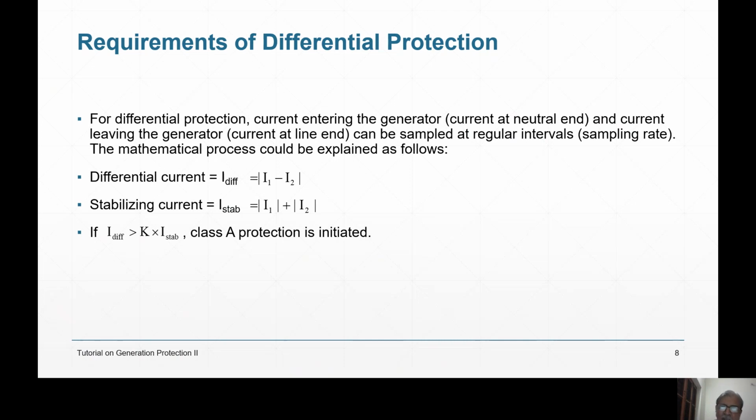In another case, I was telling you that there was an earth fault outside the zone of protection of the generator. But because of that, there was a flashover within the zone of protection between two phases because the voltage exceeded. So when differential protection operates, a good maintenance engineer never doubts the generator winding. Very rarely. It is next to impossible if I say so. Then I'm not wrong, you see.